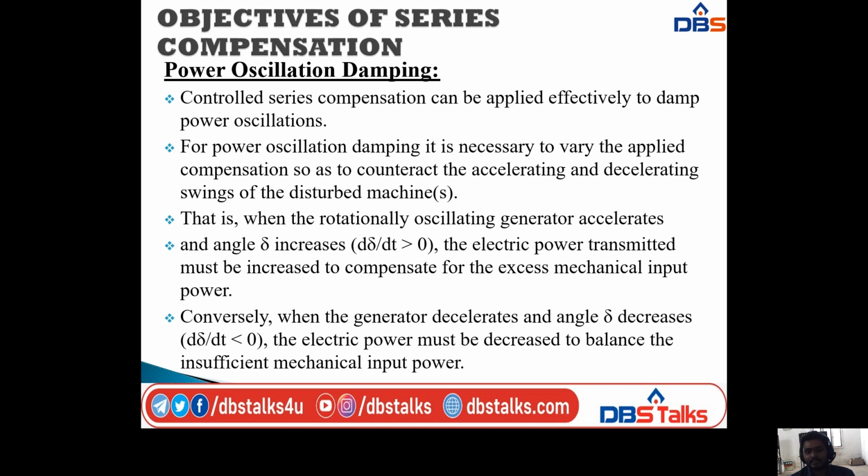For power oscillation damping, it is necessary to vary the applied compensation so as to counteract the accelerating and decelerating swings of the distributed machines.